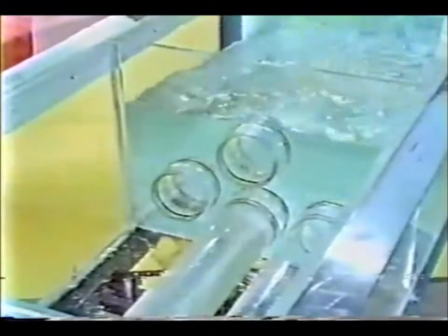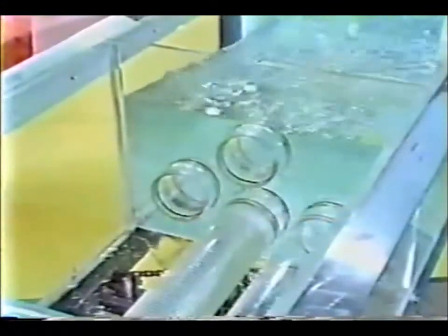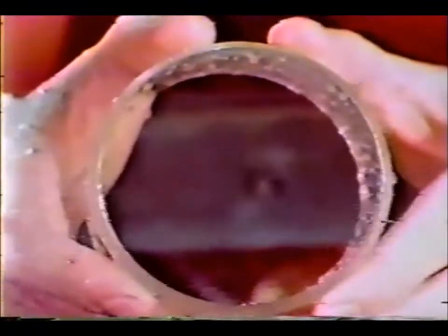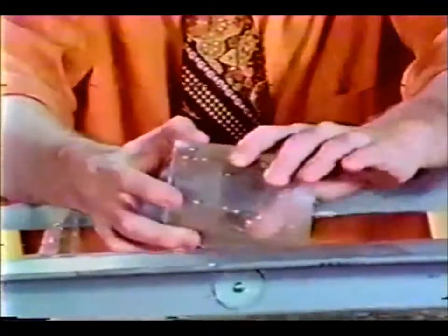Next, let's look at different entrance conditions. Several entrance types will be compared to the thin edge projecting entrance. The thin edge projecting entrance represents a metal pipe projecting from the embankment into the pool. This configuration has the greatest entrance loss of any type of culvert pipe installation.